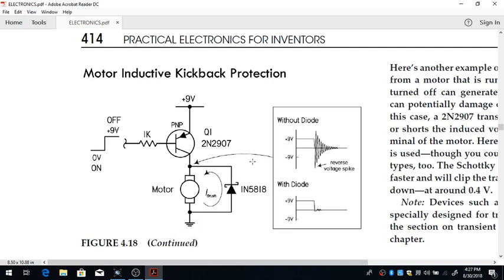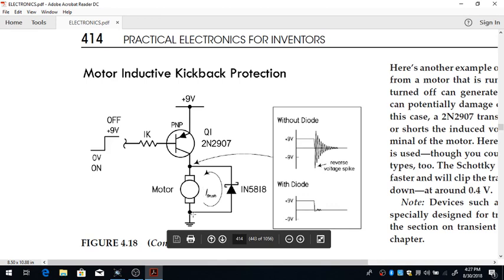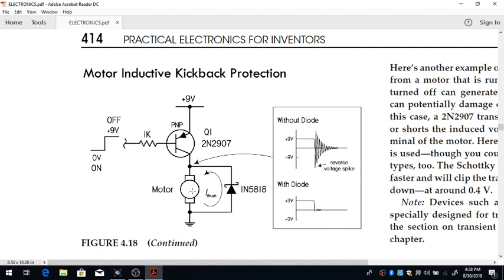You saw in my last video, I hope, that we put a diode in parallel with the relay because of inductive spikes, but there are also a lot of reverse voltage spikes. When you turn off this transistor, this motor shouldn't have any current here, but there are magnetic fields around this motor, and when you turn off, the magnetic field goes toward the motor, so the current can go back to the transistor and damage it.